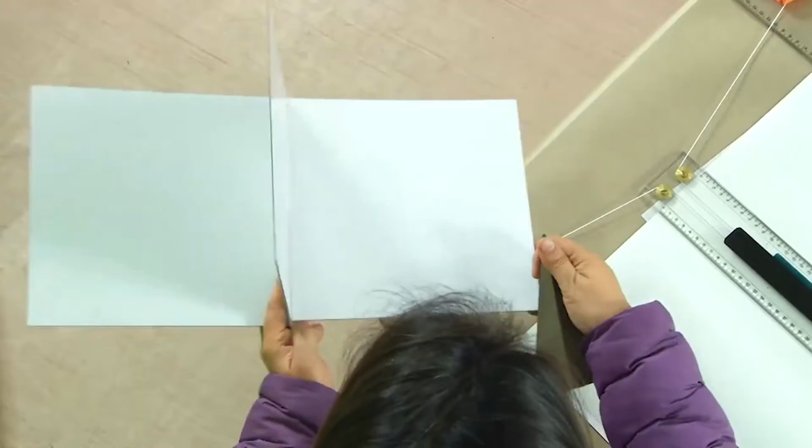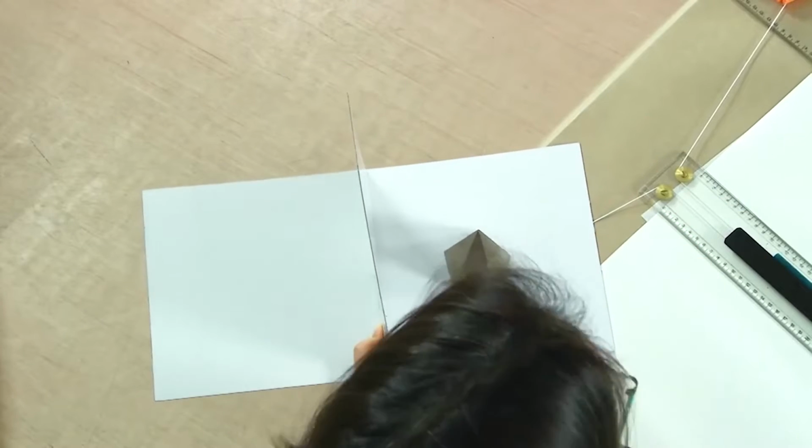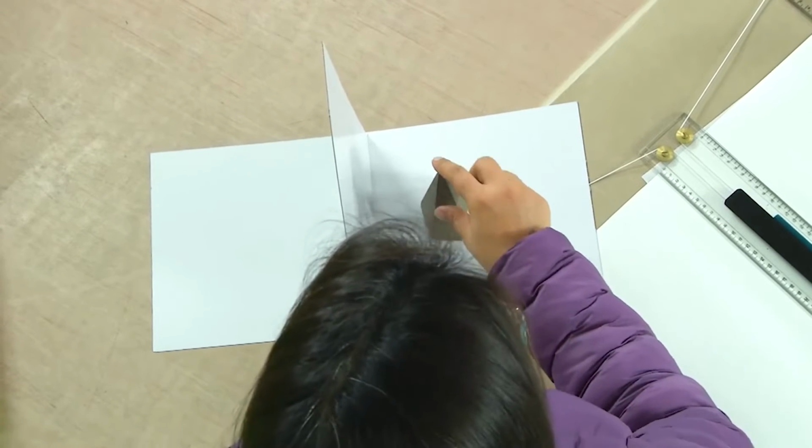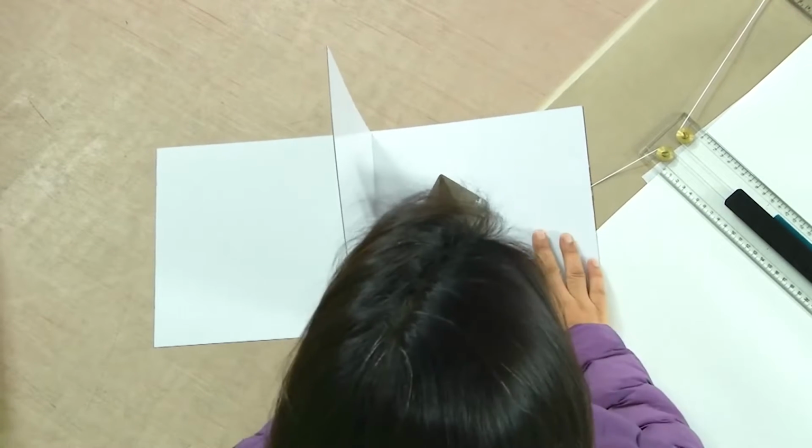Now, today we have another set of conditions where this solid, which was originally like this, is now inclined to one of the reference planes and its axis is still parallel to one of the reference planes. In this case the axis is parallel to VP, perpendicular to HP.